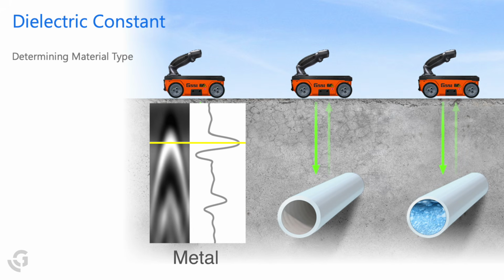Metal is a perfect reflector for GPR. The radar energy is going to bounce right off of metal like a mirror and will not penetrate through it. In the case of metal, the first strongest color is going to be white. We'll see a black, white, black pattern on our display. Note that the oscilloscope goes to the right, which we know is positive.